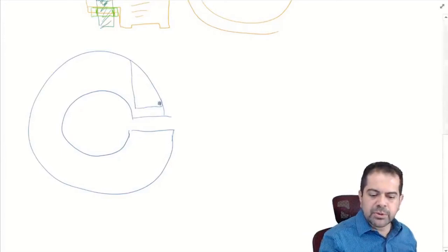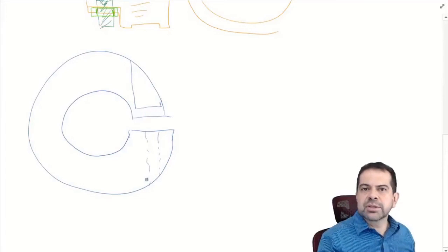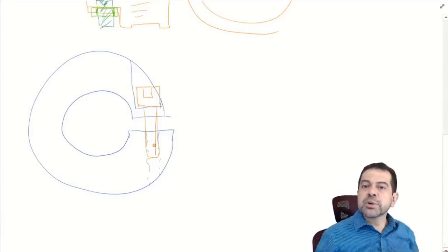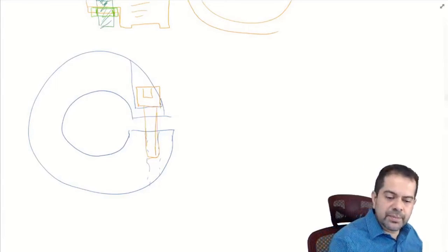Probably a counterbore and a threaded hole. Threaded holes, by the way, you probably already know this, are usually represented by dashed lines, not this thing that I was doing. I just wanted to be even more clear. But you have a socket head cap screw going through there, and when you tighten it, you're going to clamp and squeeze the shaft, right?